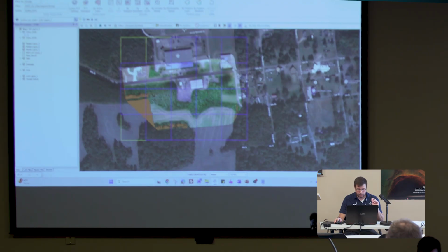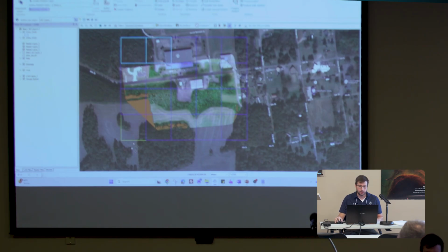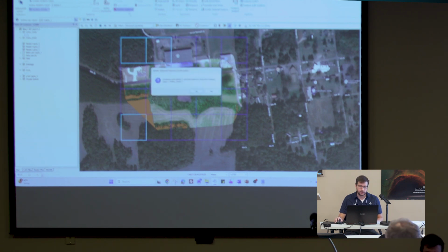But let's say you wanted that to be instantaneous and you just wanted to manually remove those tiles. I'll show you how to do that real quick. Click on the Feature Edit tab at the top. Click on the Select arrow button in the top left. I'm just going to select those tiles. Hold down Control, and you can select another tile along with the tiles you've already selected. Delete those features.